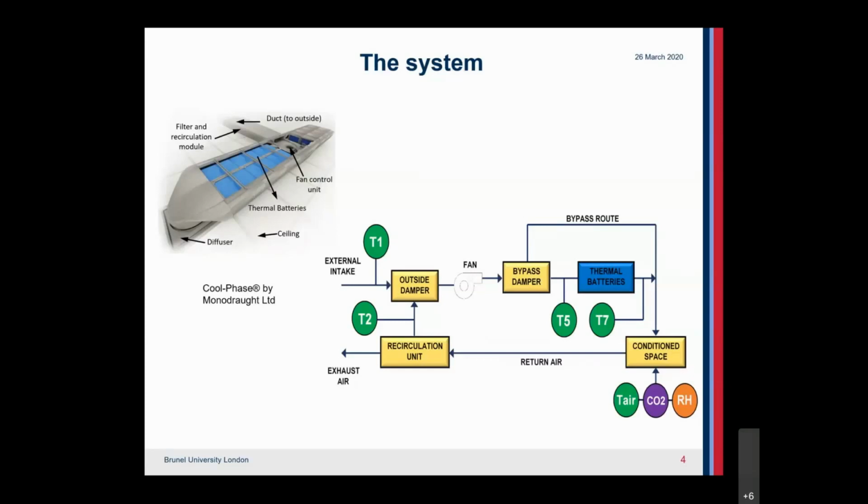The PCM storage physical size varies according to its capacity, but for these buildings, it is about 6 by 1 by 0.4 meters. The PCM is encapsulated in an aluminum panel available commercially, and each panel holds 2 kilograms of PCM, which is able to provide 88 watt-hours. Each module of the system studied has 18 panels, and the whole system has 6 modules. The PCM used is a salt hydrate with specific melting, solidifying, and heat capacity characteristics.